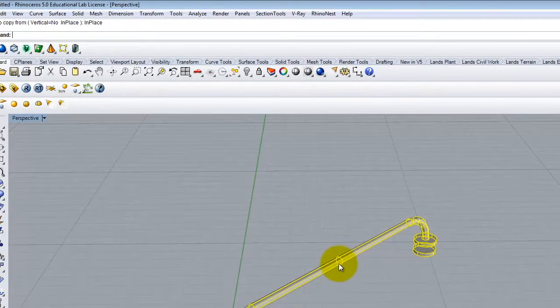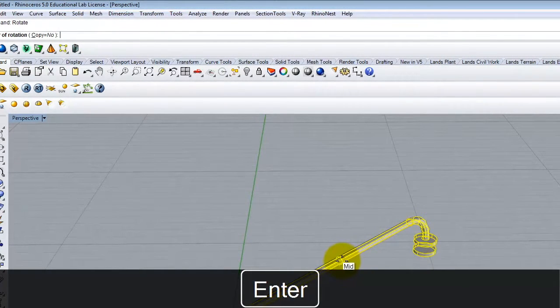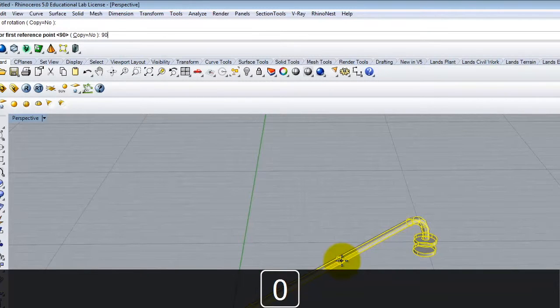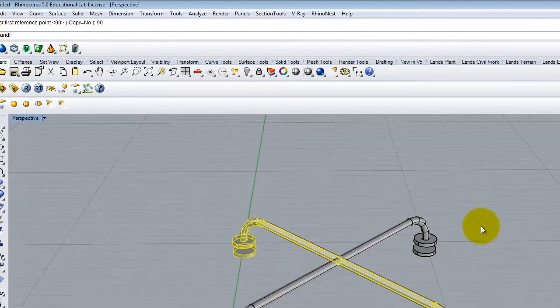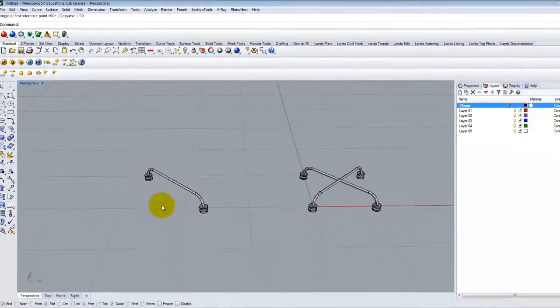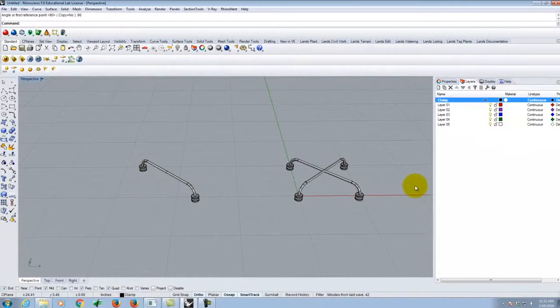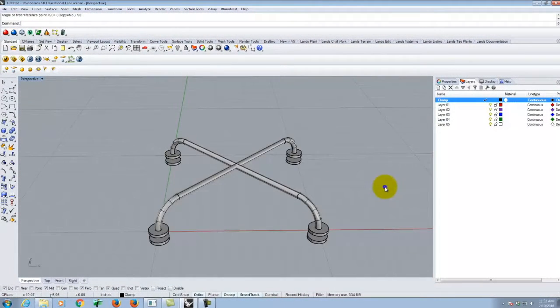And then while my object was still selected, I would go to rotate, select the center of the object, and type 90, and it would create the second object on top of the first. So it saves the move, but it's harder to see. And if you deselect during the process, you'll end up with two copies on top of each other, and you'll have to go through and delete. So I recommend, at your level, making the copy, doing the rotate, and then moving it back. But I at least like to point that out.